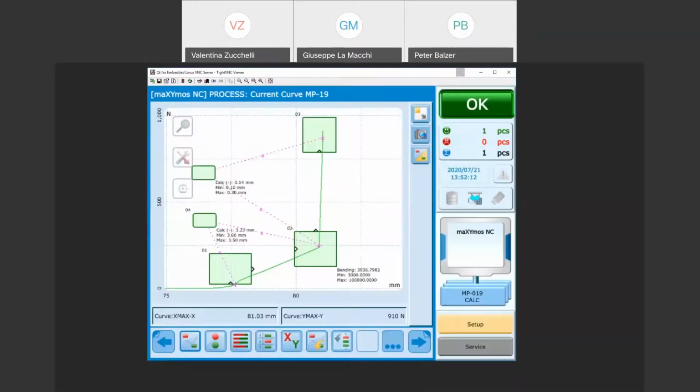Okay, so again, another cycle. Or you can also, with an additional calc element, calculate the complete distance. But now I split it up in 2. So here we have 3.23 millimeter and additionally 0.15. And yeah, you can use a third one. Then you know your press distance. So from the beginning, or from when the part is touched till the end, you know your part is pressed in this case 3.38 millimeters, if you combine these two values.